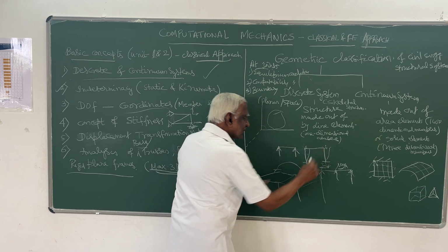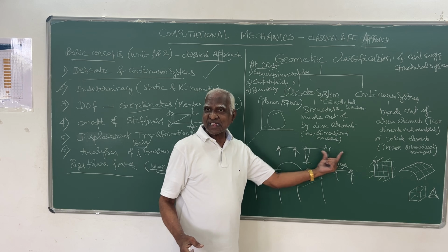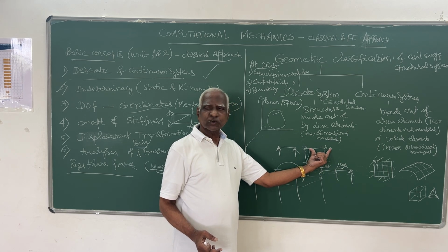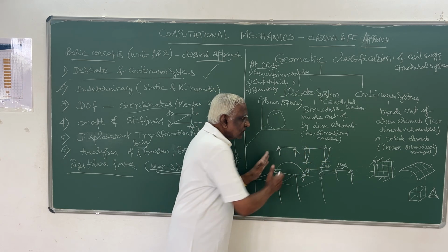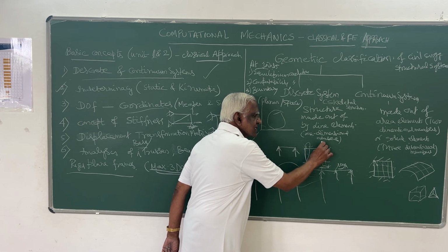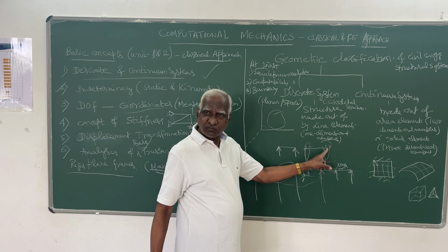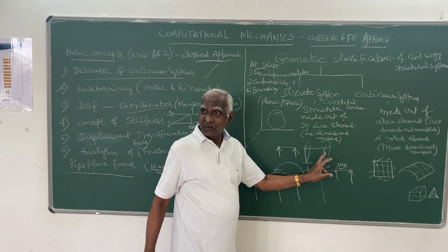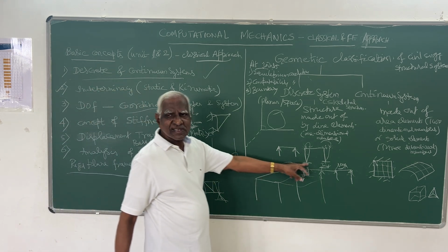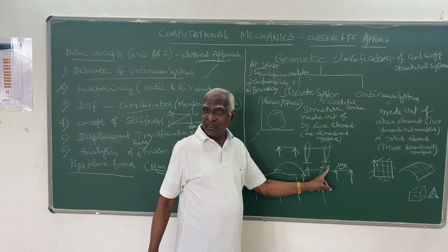Since this displacement and this displacement are equal, because bodily it has to move, I told you. Whatever is the length L, this also should be L only. So it can bodily move delta, delta. And of course, rotation is there at those 2 points. So these 2 are equal and 2 rotations. So degrees of freedom is 3. And here it is not there. So this problem is okay, it can be alone.